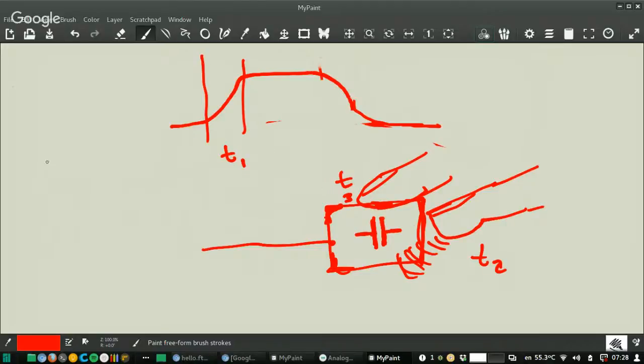There is no table to look at where you say, okay, if this time is 3 milliseconds, then I am touching the microcontroller, I'm touching this board. No, you have to calculate this. There is a research part where you get these times, and after that you do your program to set the triggers.